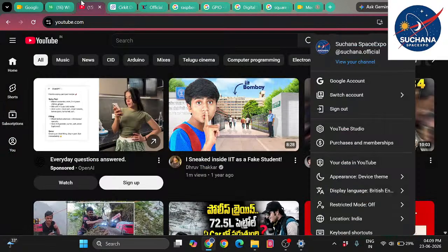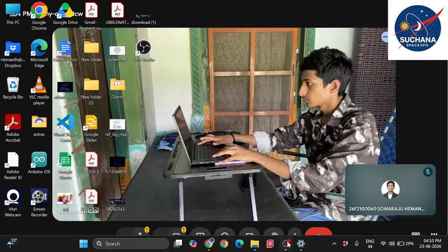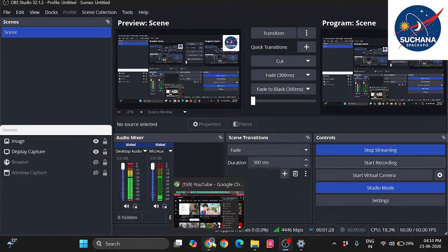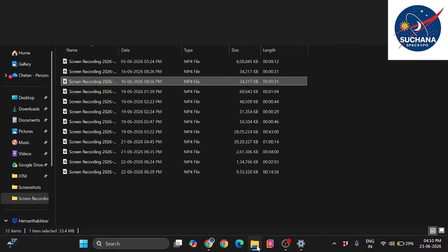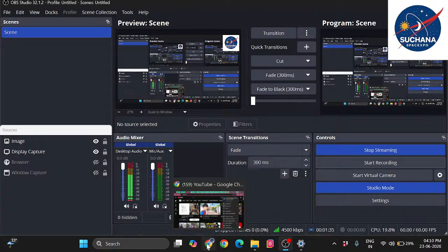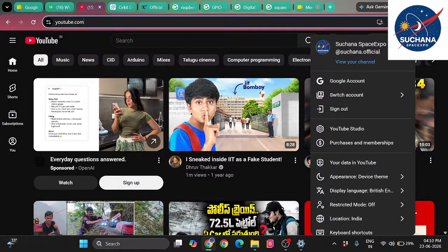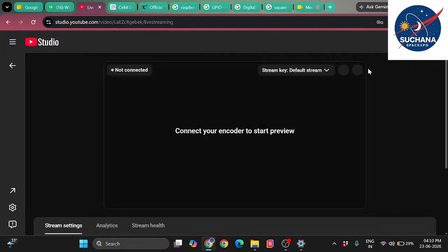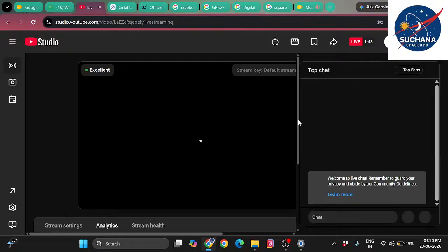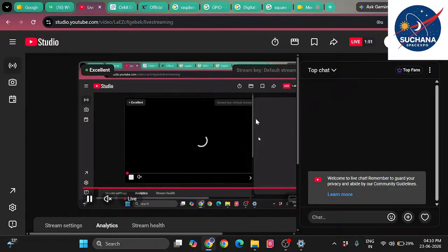You mean from day one? Okay, I'll try. Basically, it started with discussing the track width of copper traces on the circuit board, which depends upon the current flowing, the temperature and thickness. On the second day, you talked about the manufacturing process of the PCB, which includes designing the PCB, photoresist, photomask, Gerber files, fire retardant, etching process, silk screen, the different types and manufacturing of silk screens, solder mask, and you derived the equation which is required.